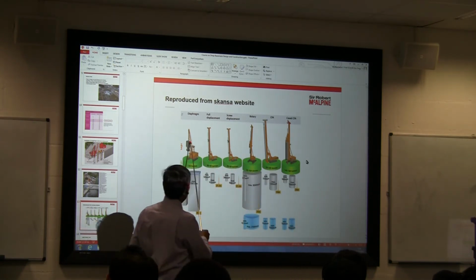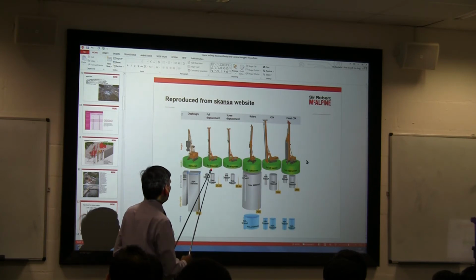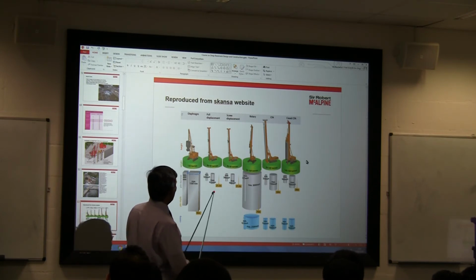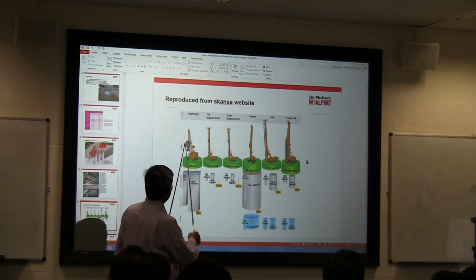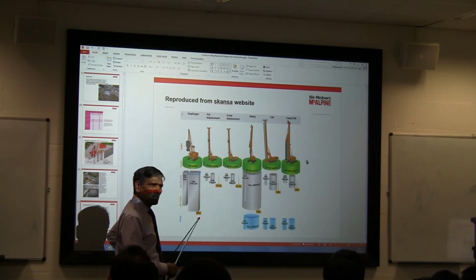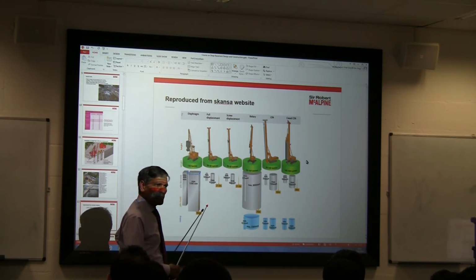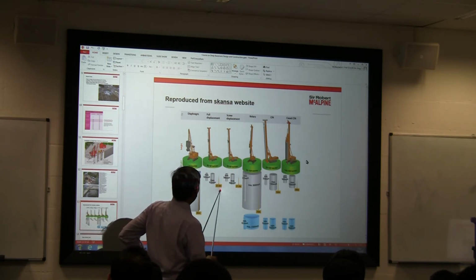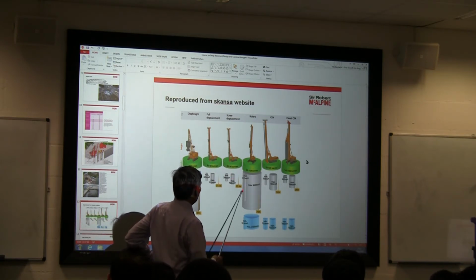So this gives you an idea of the tonnage. And then again, if you have a full displacement pile, we talk about 90 tons, and you can see the diameters and the depths we can go. You can see the diaphragm wall, you can go up to 80 meters. That's the sort of range. And this one you can go to 21 meters. Screw displacement is about 20 meters.